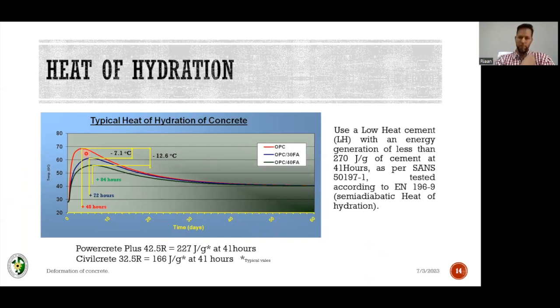You could go there, but if you imagine a cup of water that is 70 degrees, you just boil the water for a cup of coffee or a cup of tea, and you wait for it to settle down a bit to 70. That's scalding hot. That is very hot. It steams on the surface, and that's part of the problem. Much of your water then starts steaming inside the concrete as well. So that's another problem.